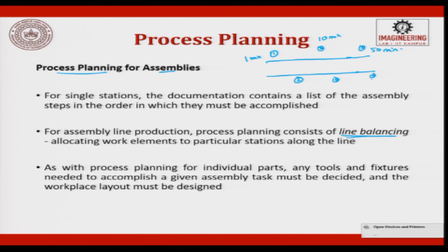So, now here it takes 2 minutes, here it takes 5 minutes and here it takes 3 minutes. If you look at it, all these machines would have done their operation, but this machine where there is 50 minutes of time, which is the 5th station, is going to take 50 minutes. Now, all the other machines will be starving for a new product to come until this fellow finishes it.